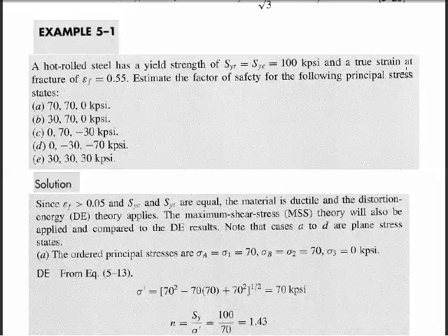These are principal stresses. And in this case we have sigma A, sigma B, and 0. So our stress element would look like a square that has 70 on both sides and no shear stress. Okay, and so these two numbers being the same, we would go to case 1.